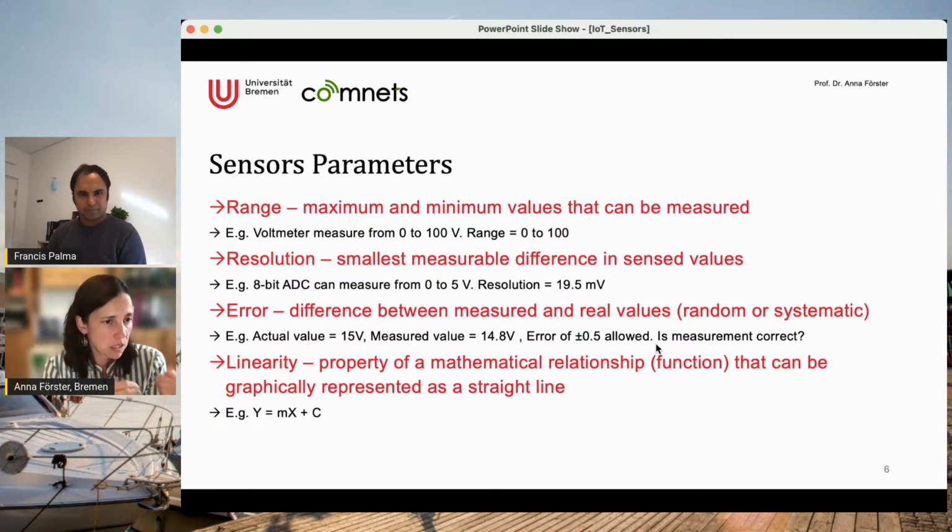So I expect this small error at these temperatures and pretty much the same properties also for higher temperatures. This is unfortunately not always true. So it can happen that you get a non-linear sensor which increases its error or its precision or its resolution depending on some environmental properties, which are typically humidity and temperature, and or direct sunlight, which at the end is temperature, is, for example, a problematic issue with sensors always.